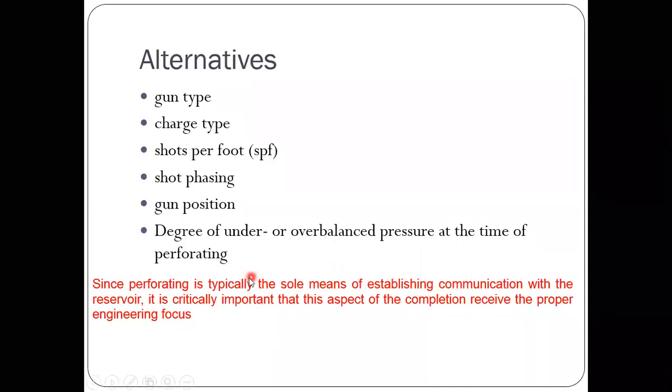So it is very important to decide the type of perforations, number of perforations, what kind of charges you are going to use, what kind of gun we have to select, and that also depends on the type of formation, formation fluid, and permeability of the formation. So many parameters affect the perforation.